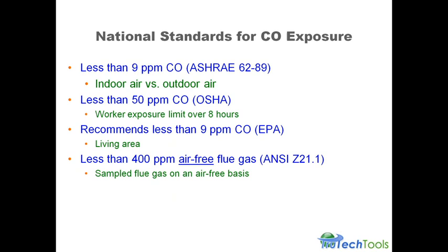So that's what we're talking about, over ambient. You can't fix what's in your air. If that's what's outside, that's what's outside. It's also going to be the same as inside. What we're concerned about is whether there is a difference between inside and outside. If I zero my meter outside, it's basically called nulling your meter. Nulling your meter means you're telling it, basically, with reference to outdoors. So I calibrate it outside, and it's going to zero out. It's going to say, I'm ignoring that 9 parts per million that's outside, because it's not an absolute measurement. It's a relative measurement. We're looking at, relative to outdoors, what's the CO indoors?